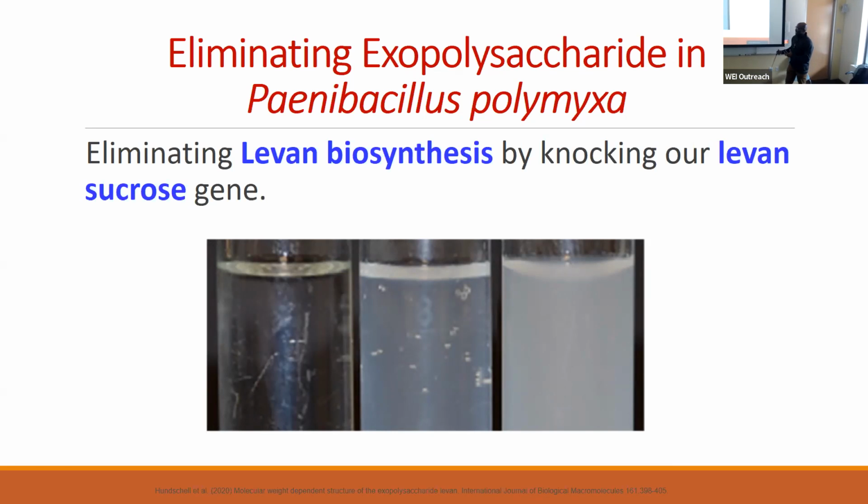The problem with this is that this compound steals a lot of carbon away from 2,3-butanediol, much more than the other compounds I talked about. And the big problem is that, apart from that, at the end of the process you have to purify your final target product. To purify it, you have to remove this exopolysaccharide, and that introduces additional steps to the process, and that increases your cost.